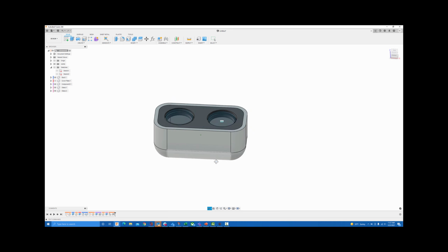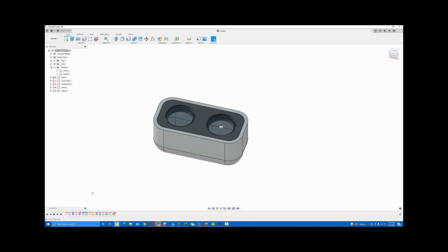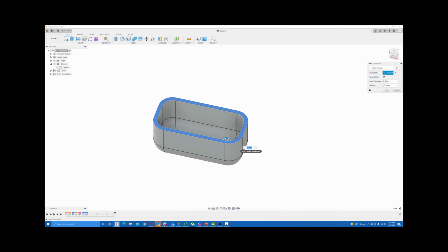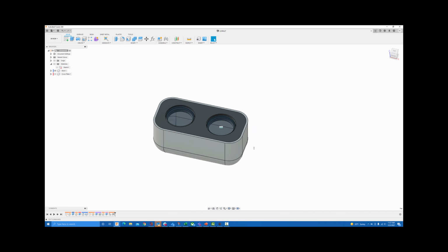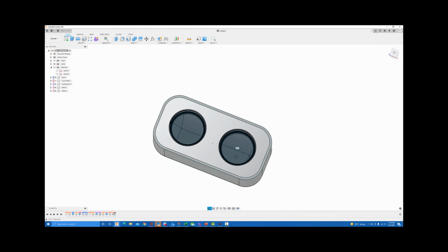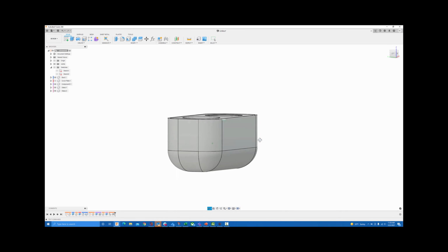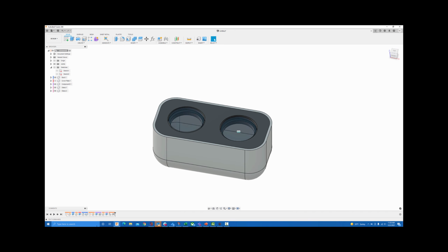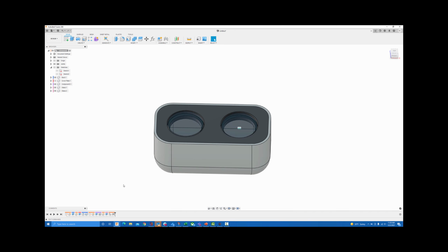So here, this is called top-down design, and we've modeled all these components basically off of one sketch, so that if we change it in one place, everything updates. Same is true if I decide the shell is too thick. We want to do something a little thinner. Notice that that plate that sat down in here is the right size to fit down in there as well. So as long as you follow through that process, you have a pretty robust model that allows you to make a bunch of different changes to the size, and everything works out. So hopefully that's helpful.